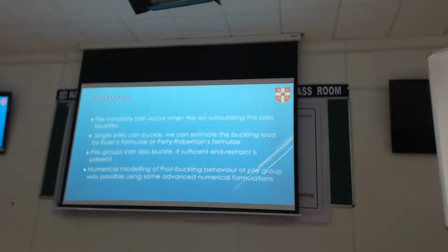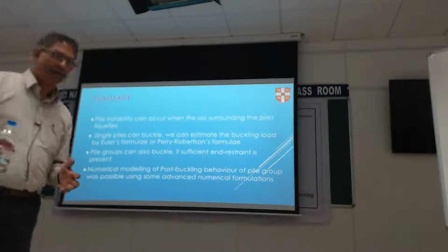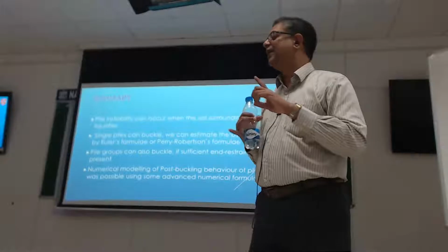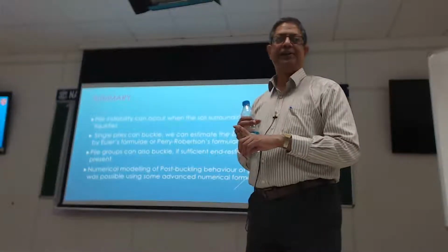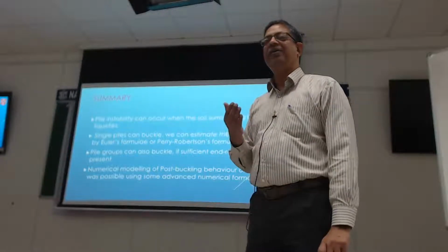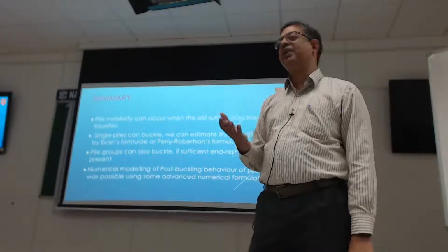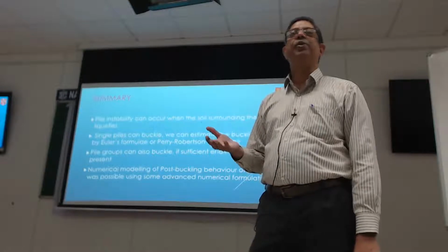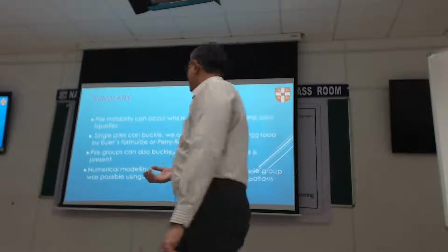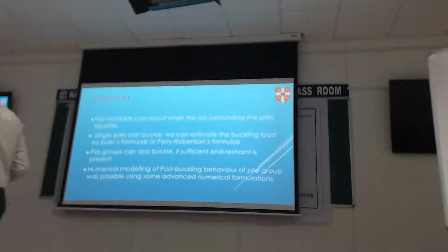These things have been published out there for a long, long time. So please estimate your eccentricity, load eccentricity, or pile imperfection. Get your eta factor, do a calculation, and see. Make sure you're not putting on these piles loads even coming close to buckling. Okay, and that's an easy check to do, and we can stop many of these piles from buckling when the soil liquefies.